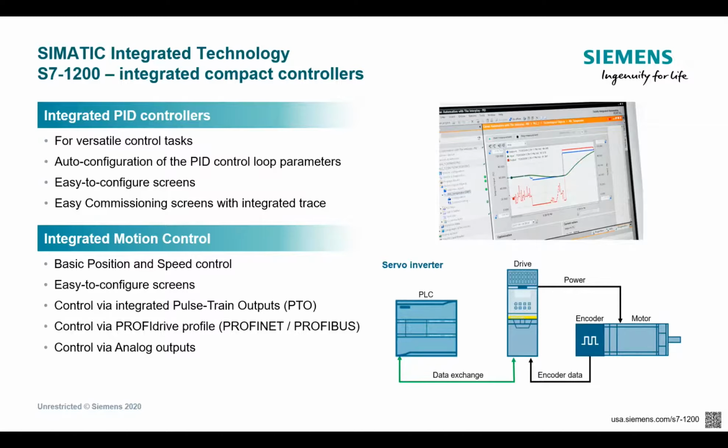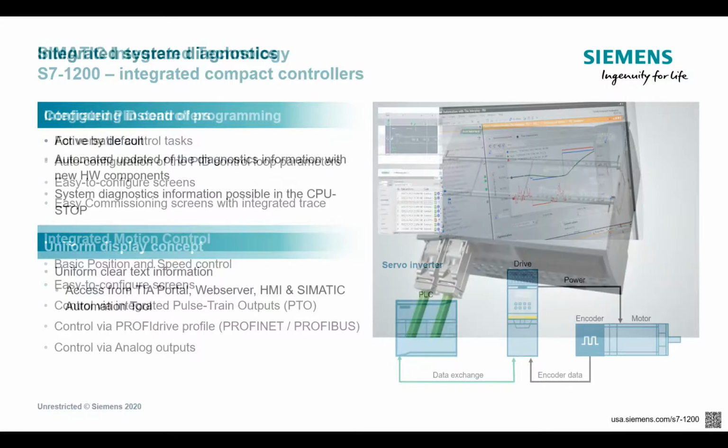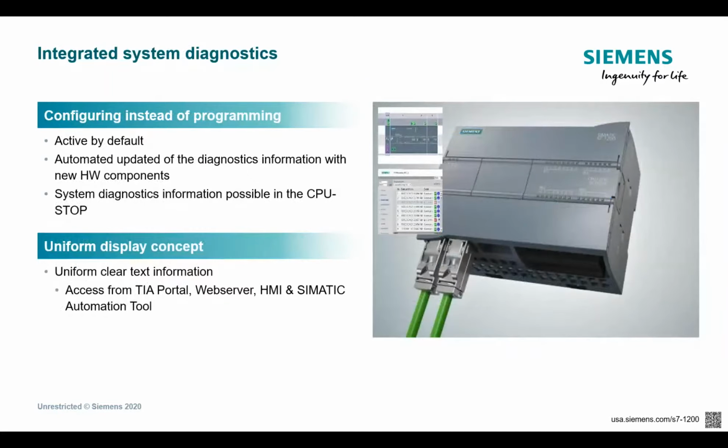And then Profinet, we can do Profinet control of a drive built into the processor. The different options that we do have for the diagnostics, you can turn on a web server on the PLC and be able to view the diagnostics on the web server itself. You can turn on an option on the HMI and view the diagnostics of the processor from the HMI. And all of the texts are built in and already written. It's clear text information.